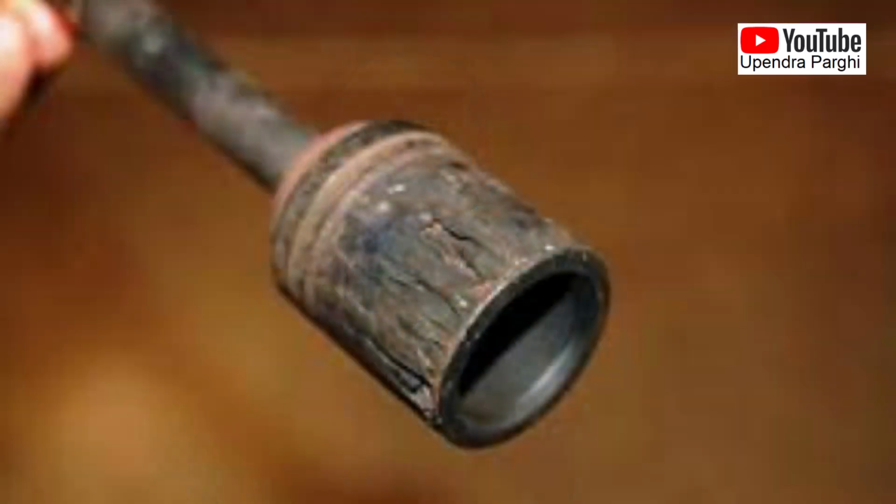As you can see in this image, the damage that is done by flashing, do note that the damage is not severe as compared to cavitation. This is because the media has changed its phases from liquid to gas and the velocity is high. However, for the cavitation, the media changes its phase back to liquid within the valve itself, due to which bubble implodes, thereby creating much higher damages. Flashing leads to erosion, loss of control, noise, vibration and reduced flow capacity.